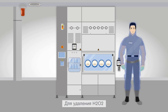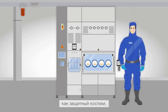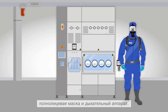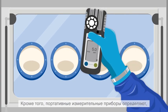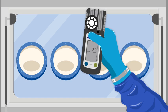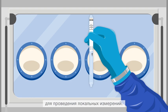To deal with H₂O₂, they need appropriate personal protective equipment, such as a protective suit, combined with a full face mask and breathing apparatus. In addition, portable measurement devices help determine if the H₂O₂ concentration has fallen below the legal limit. These devices aid in the search for the source of the leak and provide the final clearance measurement. Alternatively, disposable tubes may also be used to take spot measurements.